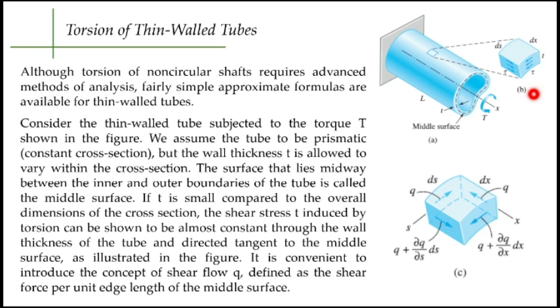That is why for thin-walled tubes, there is a mathematical concept that is used to relate the torque and the shear stress in this material. A mathematical concept is introduced, which is what we call shear flow. Okay, so basically it is just a new concept that scientists and engineers use to aid them in the analysis of torque or torsion in thin-walled tubes.